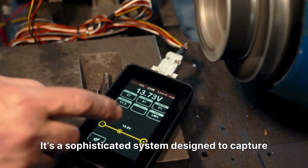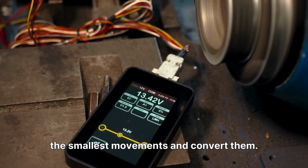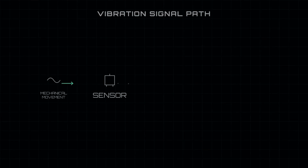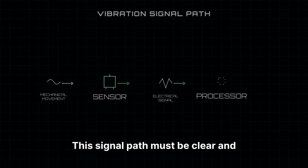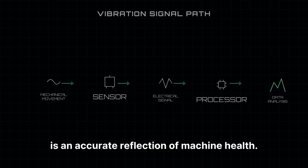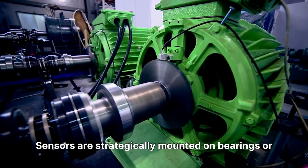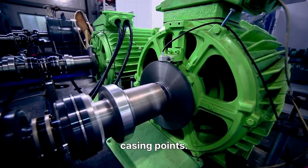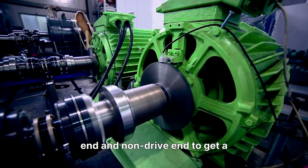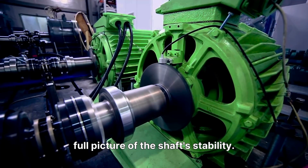It's a sophisticated system designed to capture the smallest movements and convert raw mechanical movement into electrical signals. This signal path must be clear and interference-free to ensure the data we're analyzing is an accurate reflection of machine health. Sensors are strategically mounted on bearings or casing points. We typically measure at both the drive end and non-drive end to get a full picture of the shaft's stability.